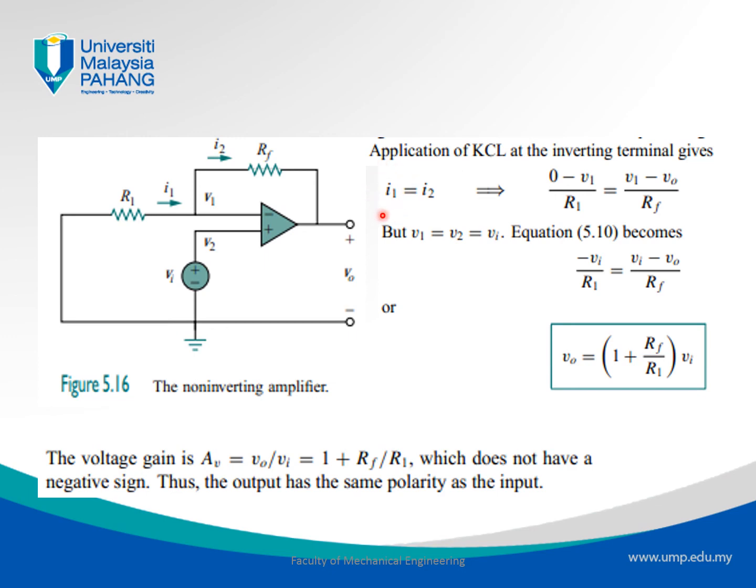So I1 is basically VR1 divided by R1, right? And what's VR1? VR1 is the potential difference between this point and this point across R1. The voltage at this point is basically the voltage of the ground, because there's nothing in between. So it's 0.